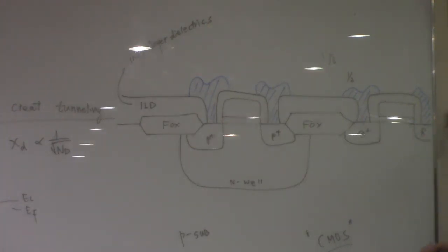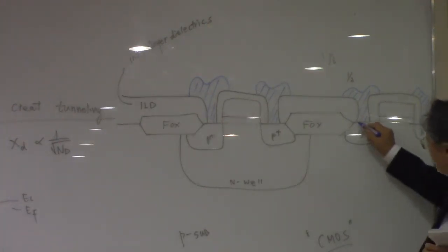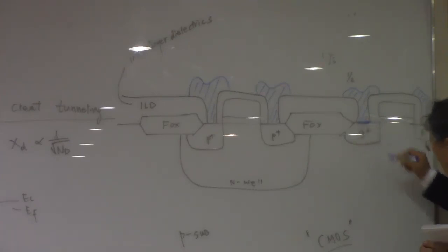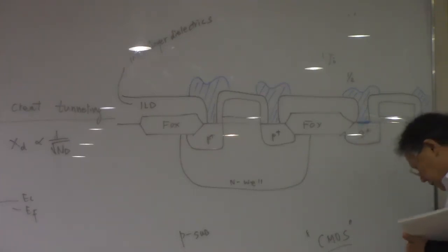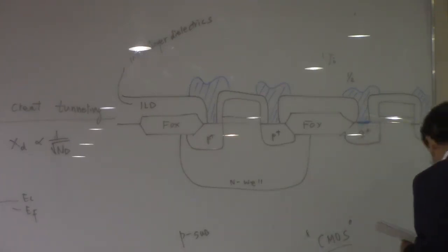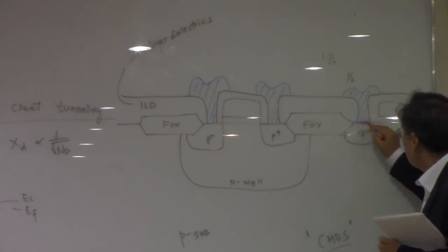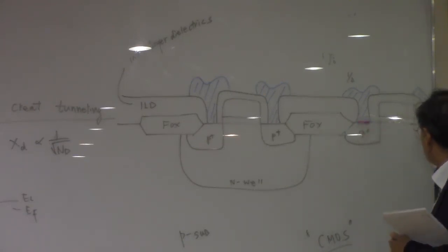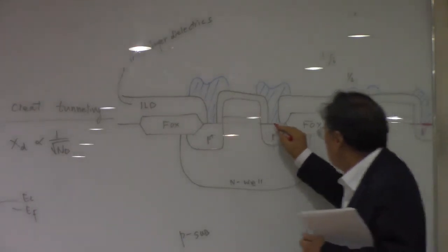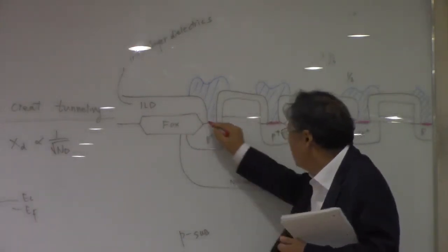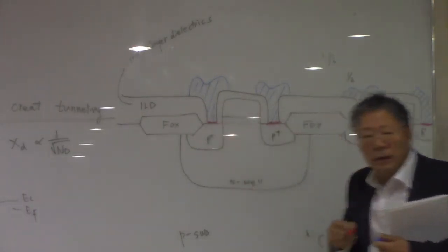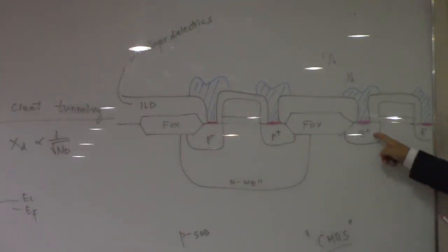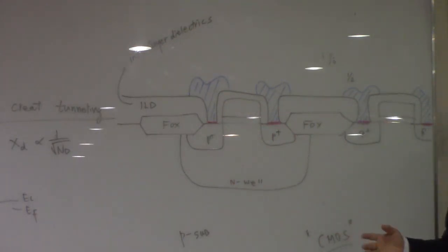Okay, and you are going to have metal-semiconductor junctions at this part. Right? You are going to have metal-semiconductor junctions here, and here, and here, and here at the same time. Okay, N plus and metals, there's no problem because there's ohmic contact all the time.